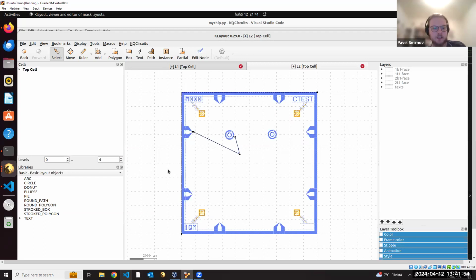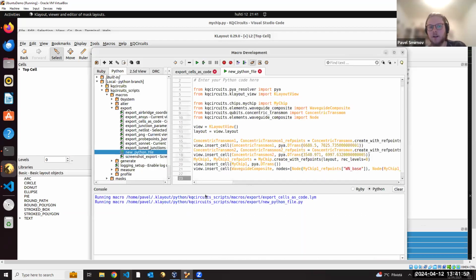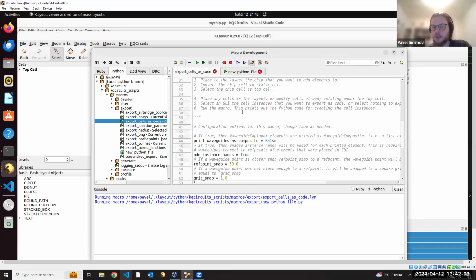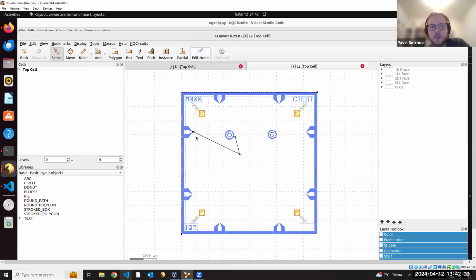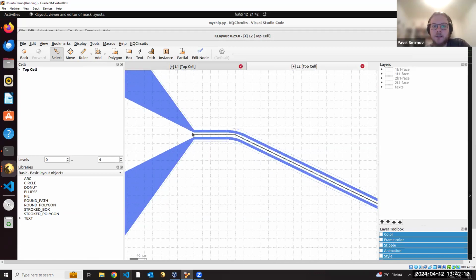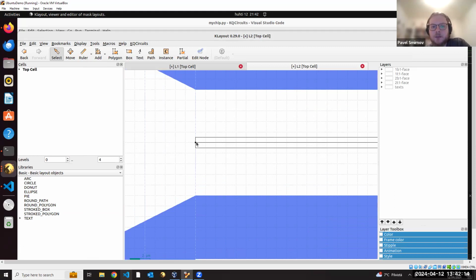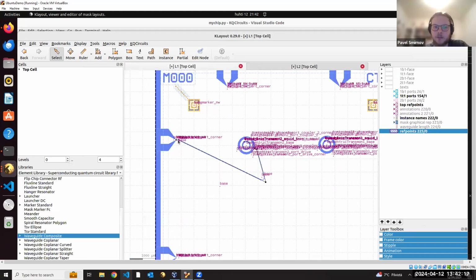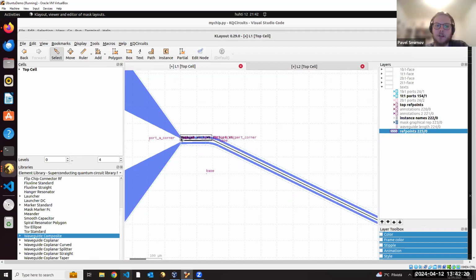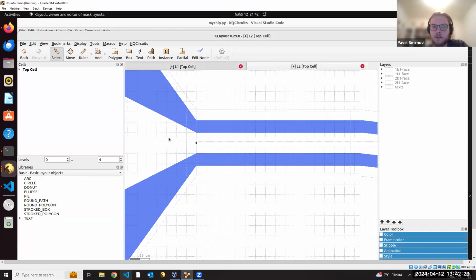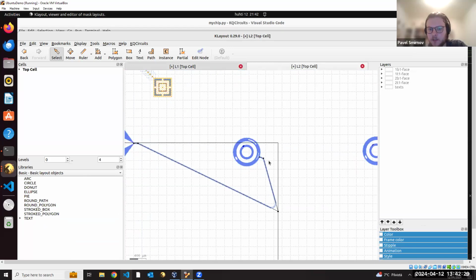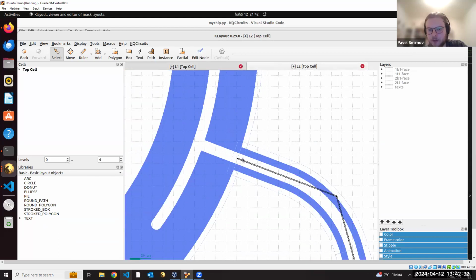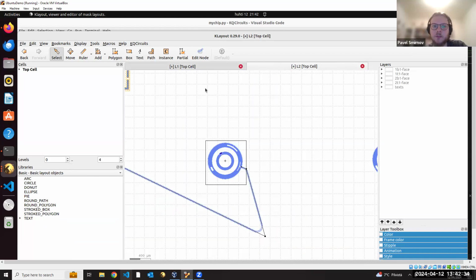So this means that this is now Python code that completely implements the design that you've just made using the CAD software. But it does a little bit of adjustments, which are actually good. For one thing, it does snap the ref points. So now this waveguide is exactly aligned with this launcher. This is something that we didn't have here because there was a little bit of a gap here. So using this tool, it also makes sure that the intended snapping actually does snap. So there is a complete continuity with how this waveguide is connected to this qubit.